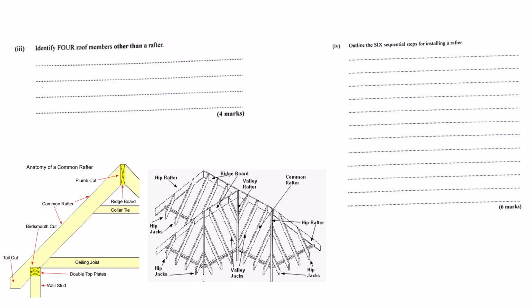All right, first step, measure and mark the rafter length accurately, based on the span and the pitch. You calculate the exact length needed. Second, you cut something called a birdsmouth joint. It's a specific notch cut into the underside of the rafter near the bottom end. What's that for? It's shaped so the rafter sits securely and squarely right onto the wall plate, stops it sliding off. Like a little seat for it, a precision cut.